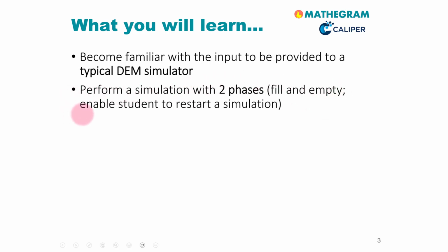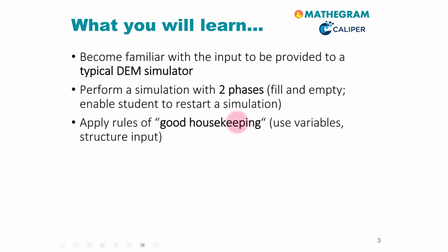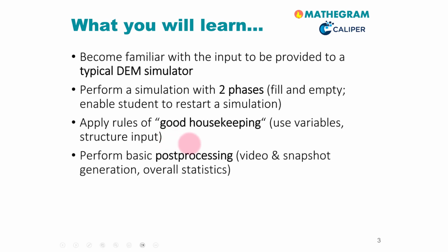The reason why we do that is to enable students to be able to restart a simulation after, for example, a filling phase. Next, we will apply rules of good housekeeping, for example, using variables in the input to the simulator, and show how one should structure the input to the simulator. Finally, we will perform basic post-processing, including video generation, snapshot generation, as well as some simple overall statistics of the DEM simulator's output.